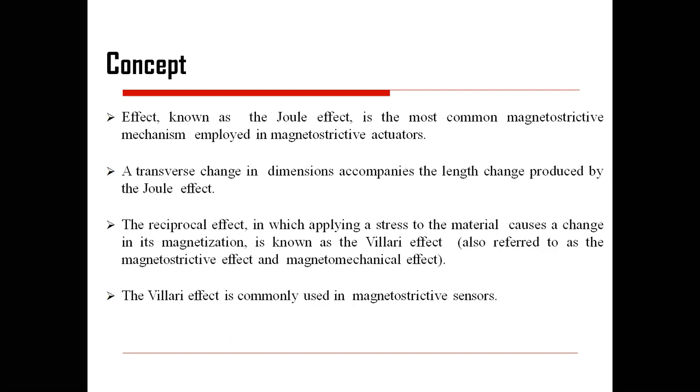In one case, the length is changing. In the other case, depending on the length, your magnetic field is changing. The change in the magnetic field is called Villari's effect, and this is opposite to Joule's effect.